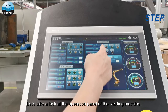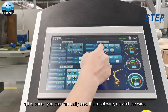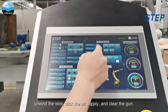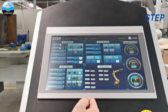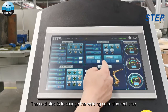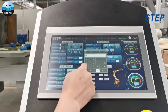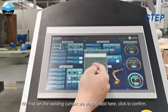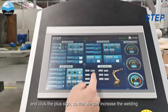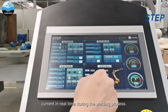Let's take a look at the operation panel of the welding machine. In this panel, you can manually feed the robot wire, unwind the wire, click the air supply, and clear the gun. The next step is to change the welding current in real time. We first set the welding current we want to add here, click to confirm, and click the plus sign, so that we can increase the welding current in real time during the welding process.